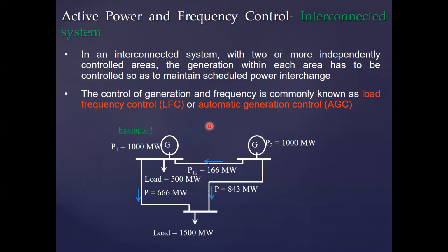But when you talk about generation control, there the change in the scheduled power flow, we apply it every half an hour, or every 15 minutes, or even 1 hour. So the time span for the operation of AGC is a little bit shorter compared to the economic allocation for the scheduling of the power flow. That is a little bit different.